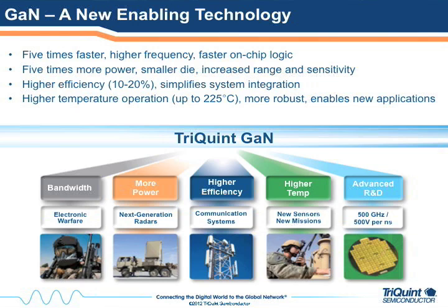Bandwidth. We're producing products with much higher bandwidth than we did for GaAs and achieving much higher power and PAE targets over that bandwidth. More power. That's really what GaN has been bringing to the table for the past several years: power. And that's how everybody sees GaN, higher power density. We've been supporting EW and radar as well as communication markets with increased power products only available through GaN technology.